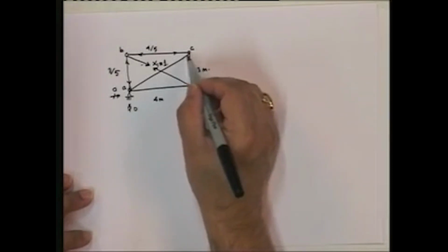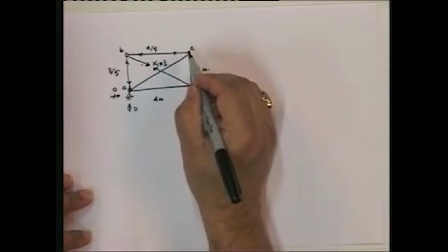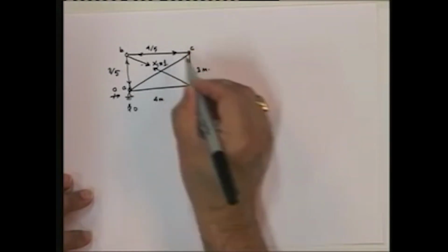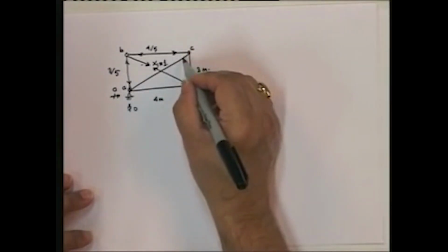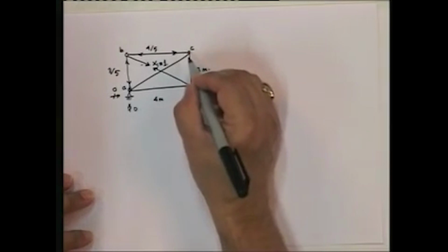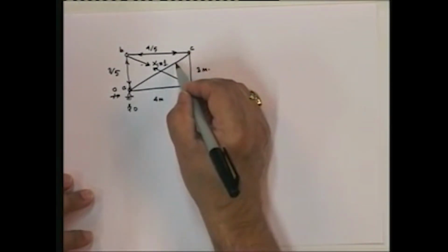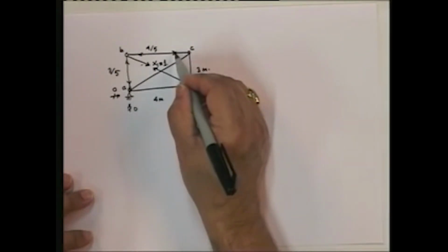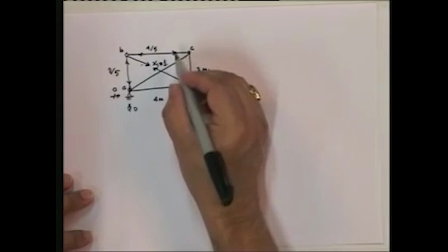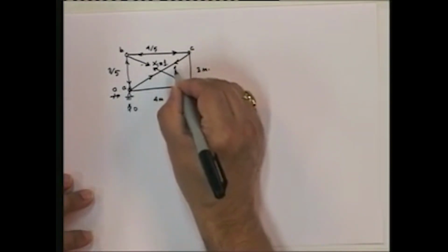Okay? And now let's look at the other force. Let's look at this. If you look at this particular situation, okay, what's the force? I know this force. What are the two unknowns? I don't know the force in this member and this member. Well, sigma fx equal to 0 and sigma fy equal to 0 will give me, what will sigma fx equal to 0 give me? That the force in this member, the horizontal component of this, plus this is going to be equal to 0. So if you do that, you will see that this works out to 1.